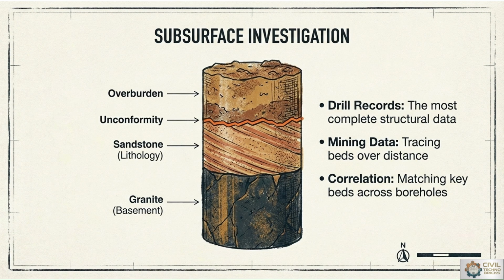When we drill, or take a sample from the subsurface investigation of any type of roadway, the sample looks like this, with n number of layers of rock, soil, or combined rock-soil texture. At the basement there is granite, which is a hard rock. Above that, with reference to the lithological characteristics, sandstone is available.